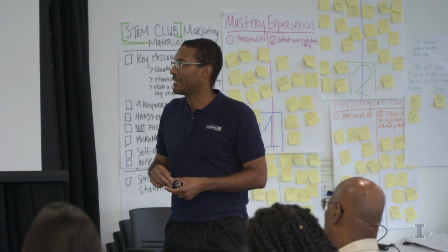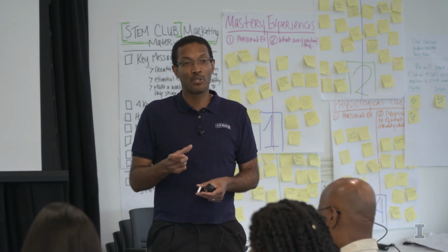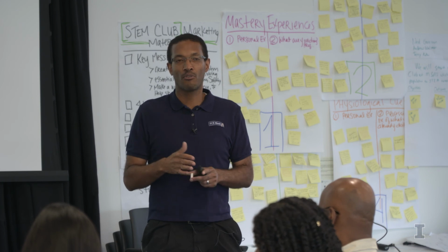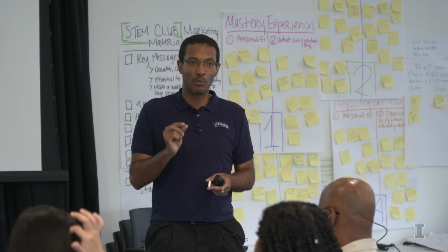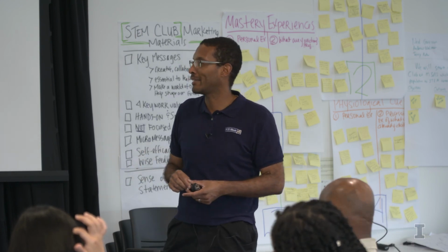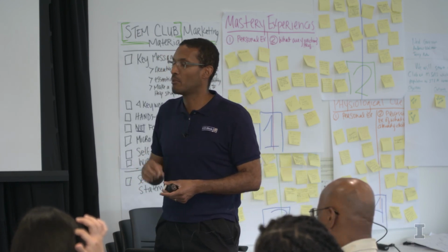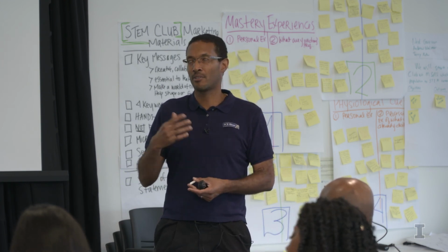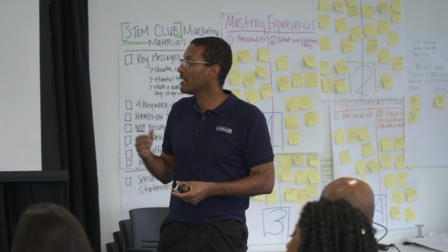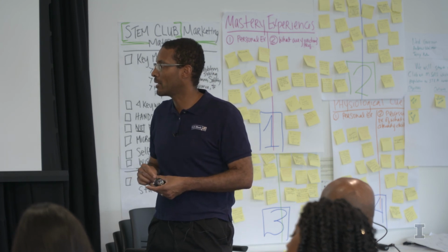The blue LED, however, the energy for a blue photon is 2.9 eV. It's so far away from 1.5 that there's no hope of it turning on. The red will turn on even though the voltage is slightly less than the actual energy. The reason is that there's thermal energy, and that thermal energy is enough that there are a few carriers in the conduction band that can recombine and produce the red light.